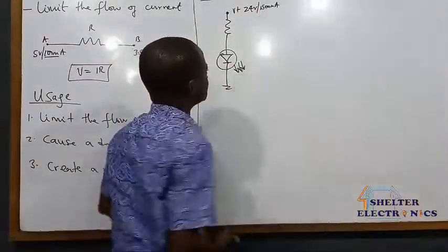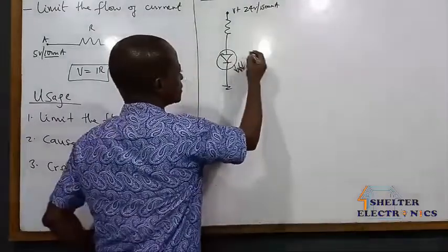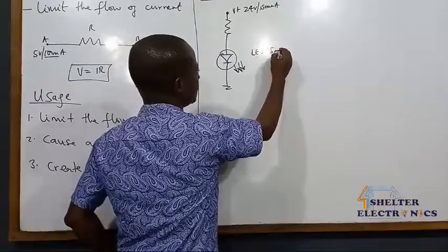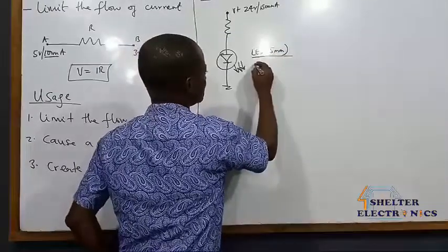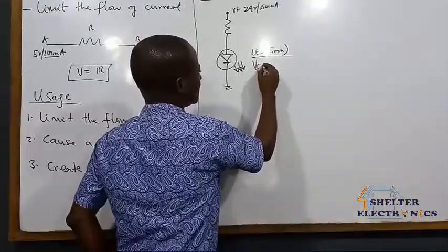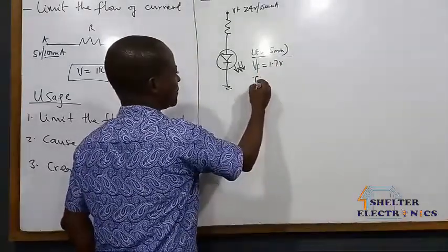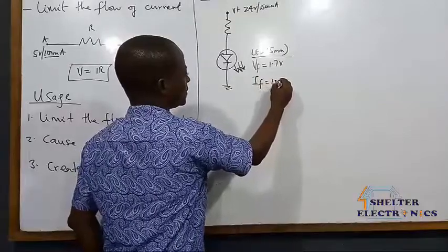1500 milliamps. But then such an indicator module will always have a light emitting diode, in most cases a 5 mm light emitting diode, that will not take in more than 1.7 volts as maximum forward voltage and the maximum forward current of 10 milliamps.